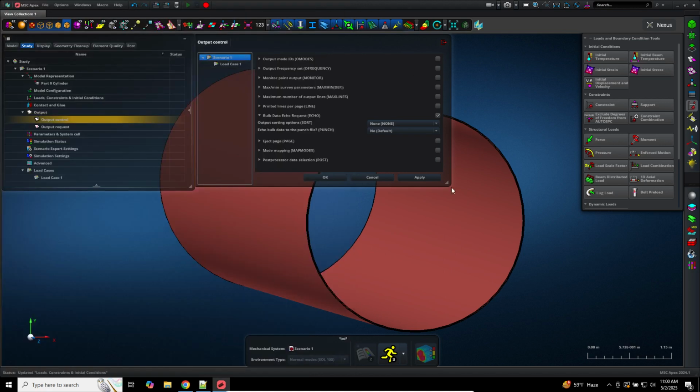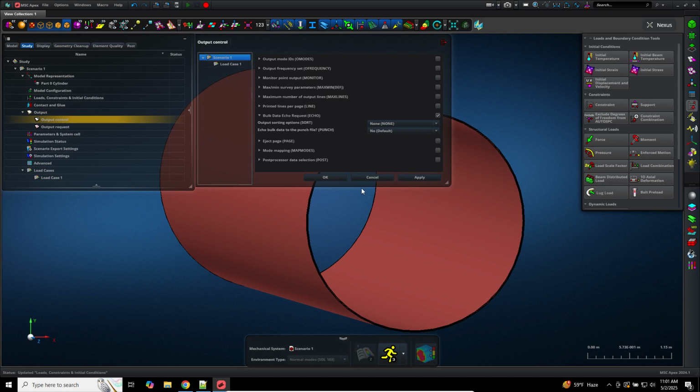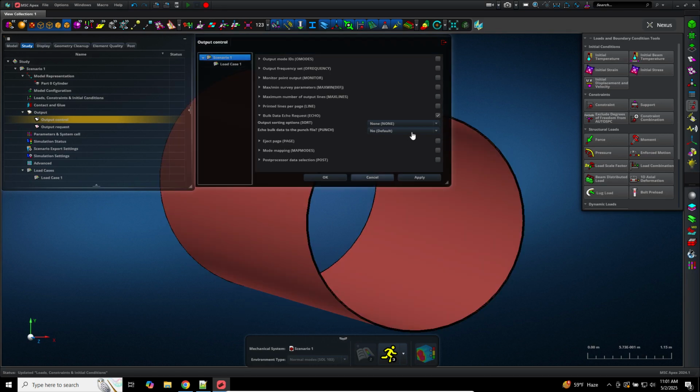If my final Nastran model is 10 gigabytes big, it's going to write out the whole model again, 10 gigabytes to the output file. Here I'm saying, you know what? Don't do that. That's not what we want. So I'm going to set echo to none. Do not select the option none, default, none; the program ignores that selected option. Select this bottom option, none, parentheses, none.